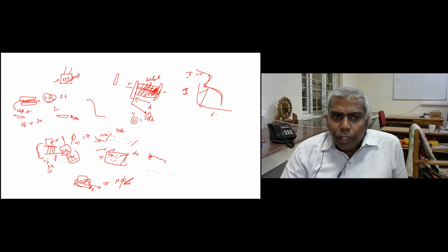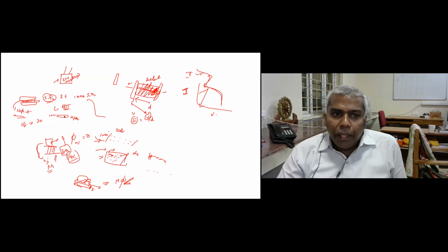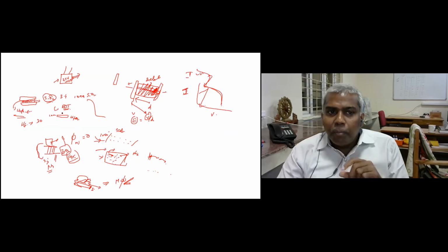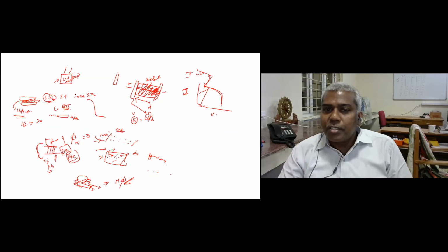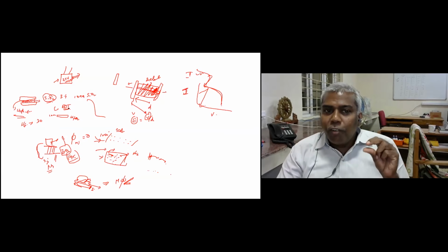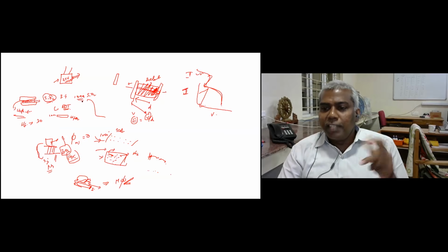For example, you can coat 1 nanometer of hafnium oxide. This will behave like 10 nanometer of silicon dioxide. They define this as equivalent oxide thickness, EOT. So physically, the dimension of the material is 1 nanometer and the device thickness is reduced, but it is equivalent to 10 nanometer of silicon dioxide. So this thickness is reduced, but works like 10 nanometer equivalent oxide thickness.